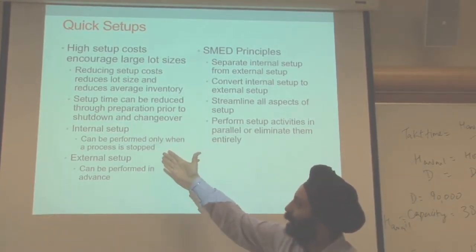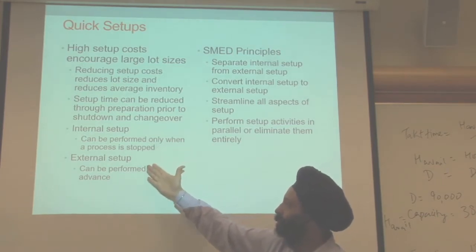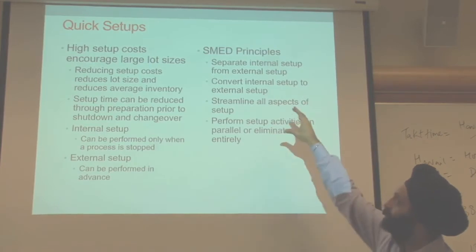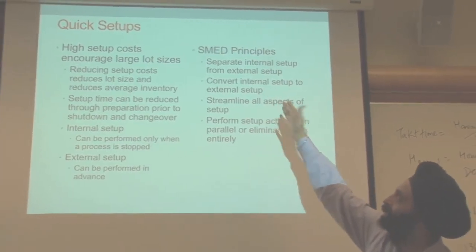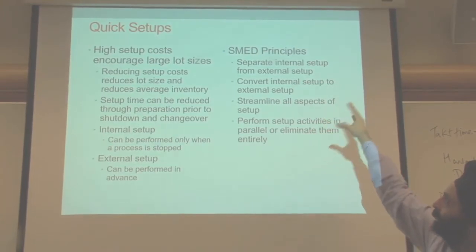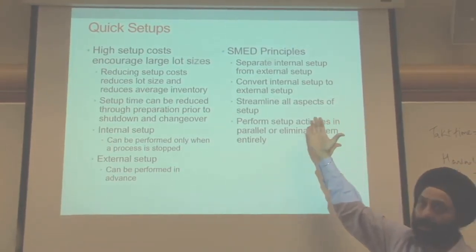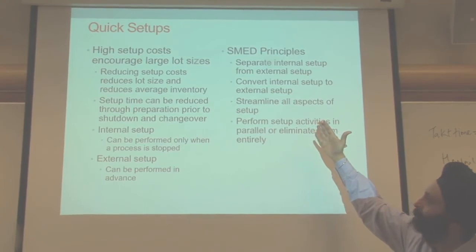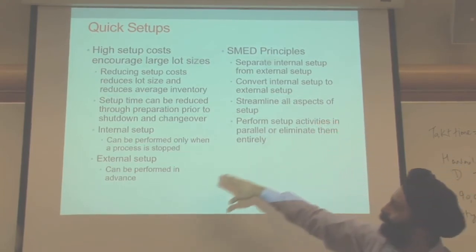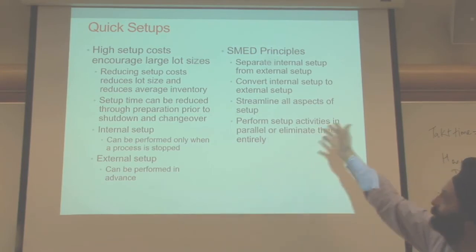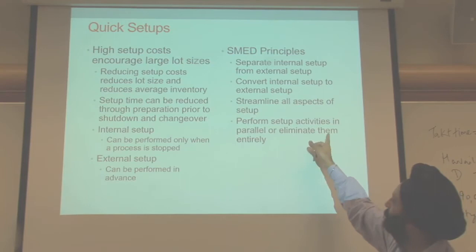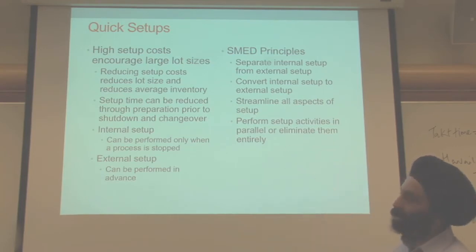Internal setup can be performed only when a process is stopped, and external setup can be performed in advance, ahead of time. Single minute exchange of die, or SMED, is a principle: separate internal setup from external setup, and convert internal setup to external setup so that you can perform things in advance. Streamline all aspects of setup, perform setup activities in parallel, and eliminate them entirely.